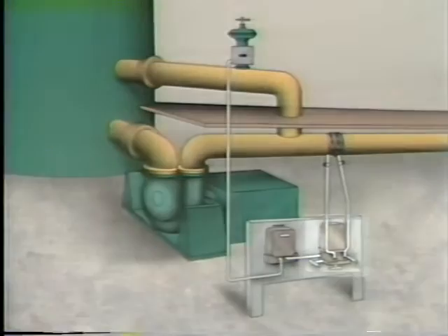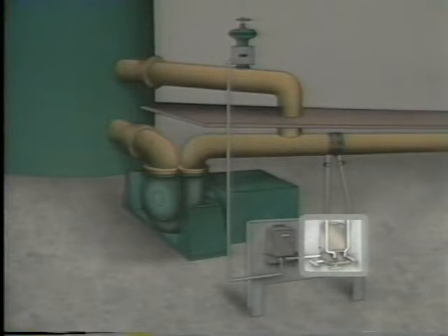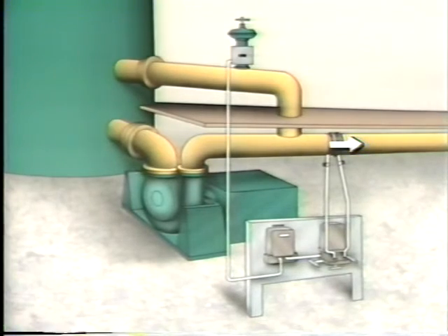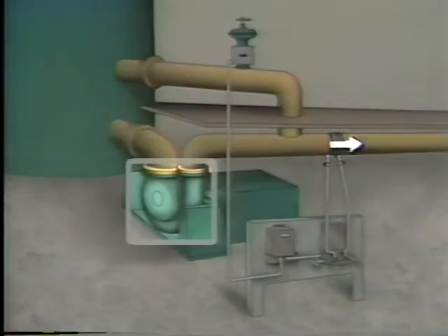In this system, the transmitter monitors and measures values representing flow through the discharge line. We know that if flow through the discharge line changes, that flow through the pump will change as well, although we don't know exactly what the flow is through the pump because the control system is not monitoring flow through the pump.